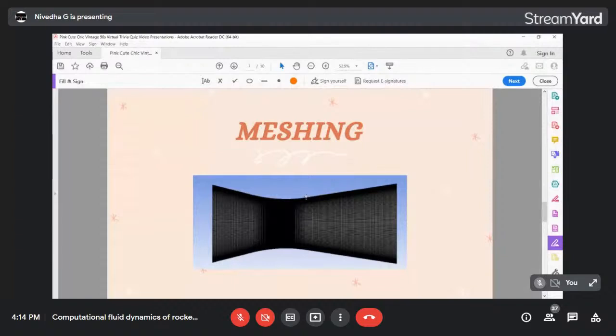So this does not belong to a de Laval nozzle, but it is still a straight CD nozzle, just a little bit curved. That's it. It is only to eliminate your shock formation. Here I have a number of nodes amounting to 1 lakh, because that is when the solution is considered accurate or proper. Any node number below 1 lakh is considered that you can make it more accurate.